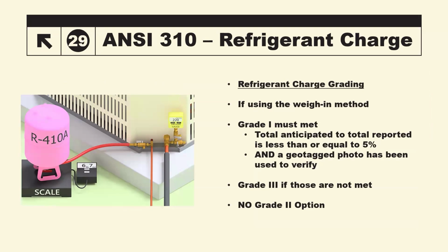If you're not familiar with HVAC and how those things are done, when the condenser shows up new, 9.5 times out of 10, the condenser has refrigerant in it and the valves are closed. Once the system is installed and the line set is installed, you open the valve, and as long as it meets the line length of the line set, the refrigerant that's in the condenser should be close, if not accurate, on the installation.